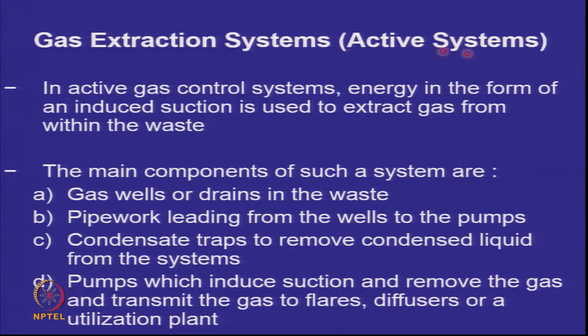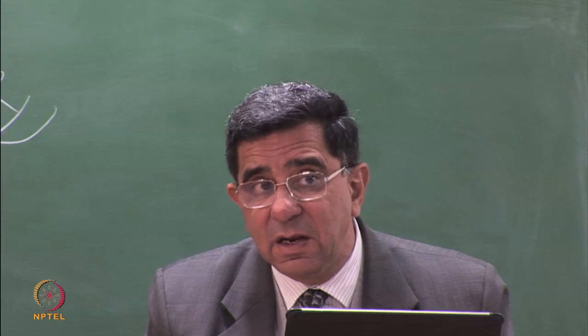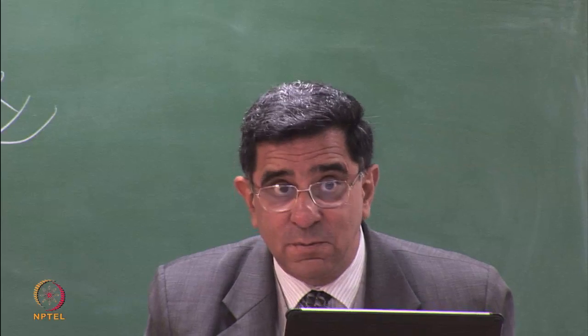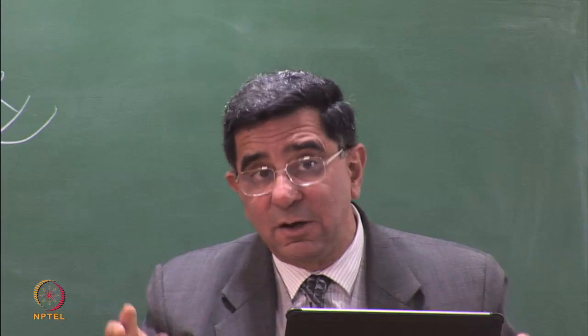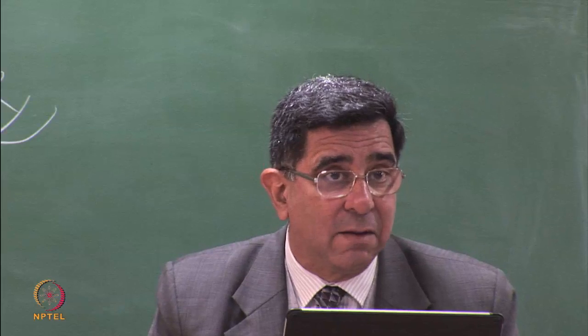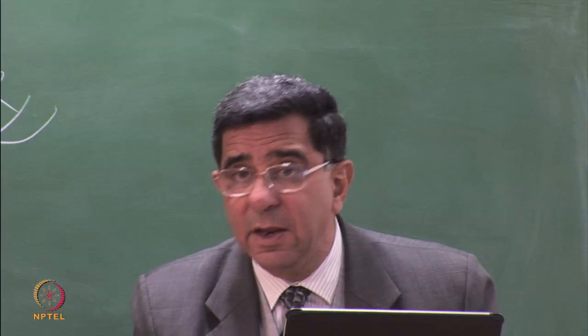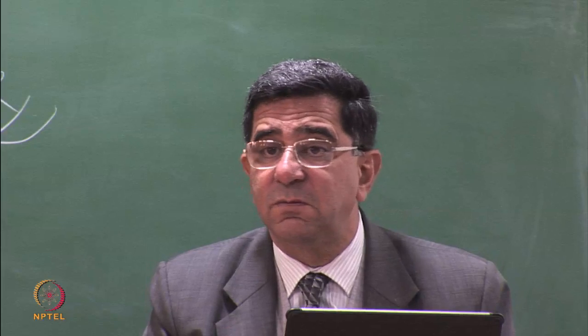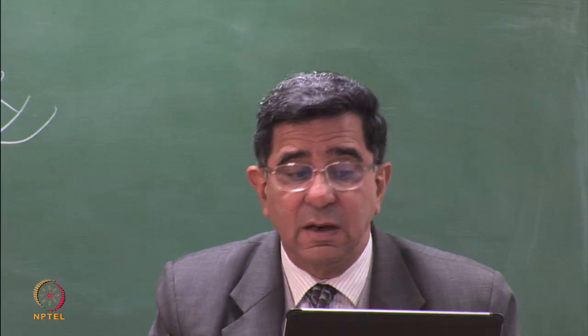So in the active systems, you are inducing suction, nothing else is changed, and that is used to extract the gas. If you keep the system under negative pressure all the time, no methane is going to escape, and therefore landfill fires will not be there. But we have to make that investment, and you have to put a cover at the top. So if you don't close your old waste dumps and you don't do your gas collection properly, you are going to continue with this problem of fires and smoke on the landfill.